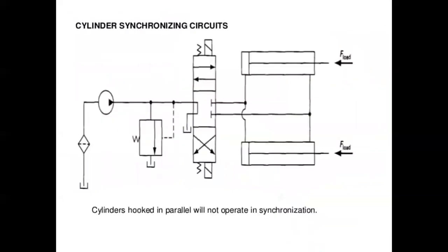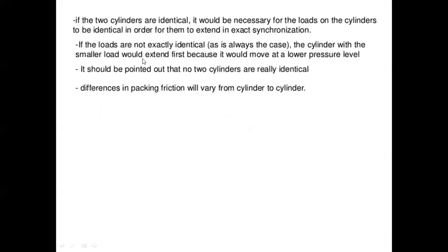Synchronization hydraulic circuit. Cylinders hooked in parallel will not operate in synchronization. If the two cylinders are identical, it would be necessary for the load on the cylinders to be identical in order for them to extend in synchronization.